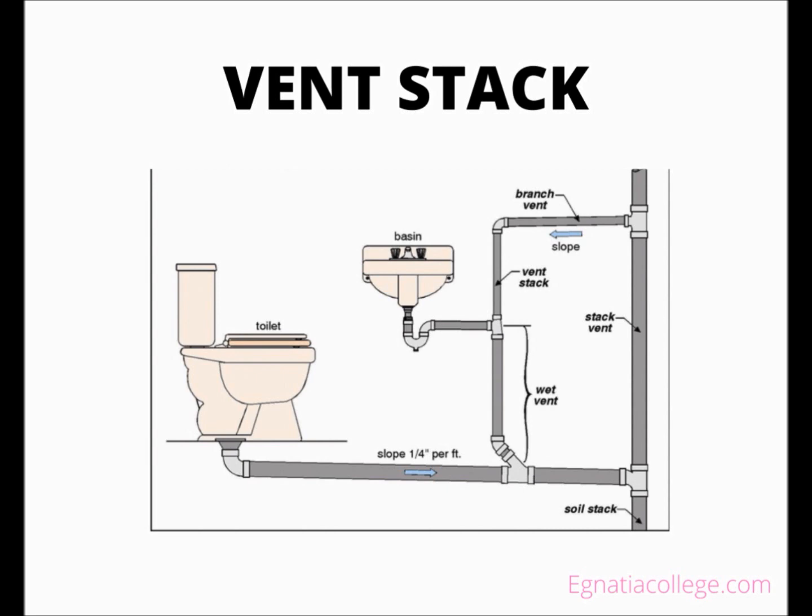Some codes require a cleanout to be installed at its base. The vent stack can transition horizontally without requiring a relief vent. However, as with all horizontal vents, it must have adequate slope to prevent moisture from settling and obstructing its airway.